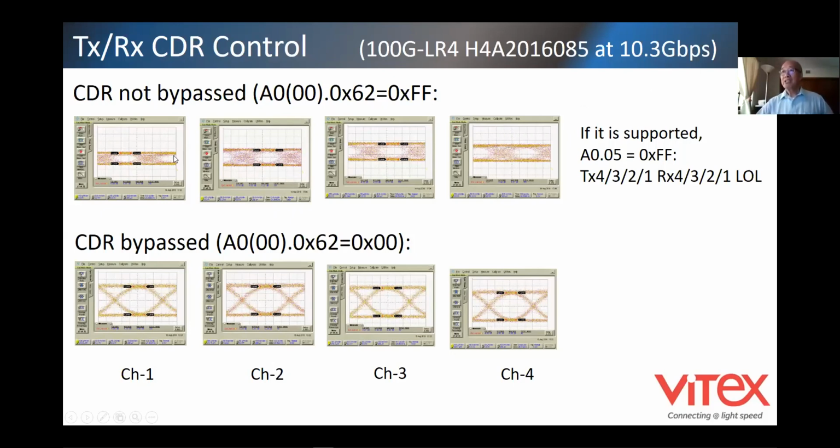What happens is that when you run it, you have jitter like this. It's simple, because the clock cannot be regenerated. The clock is supposed to lock on to the 25G, but now the data is 10.3. You can imagine there's so much jitter. The clock tries to reclock it, so there is humongous jitter here. But keep in mind, the center should be doable for the CDR to sample. That's why it keeps trying to lock.